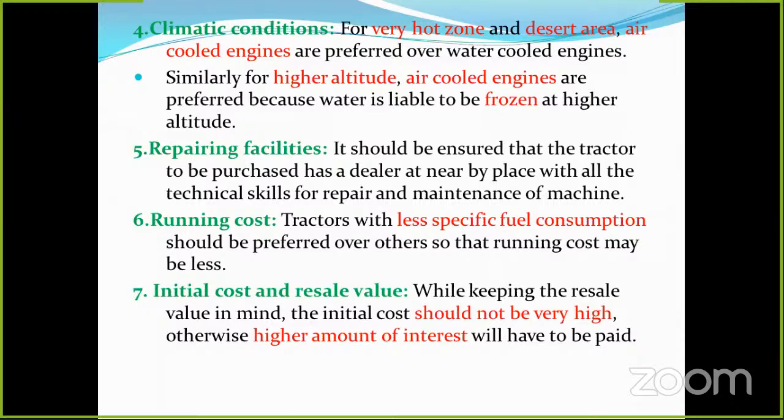Next, running cost. Some of the diesel engines may have very low mileage, or some of the models will give higher mileage. So depending upon running cost also, we have to select the tractor. Next, initial cost and resale value.